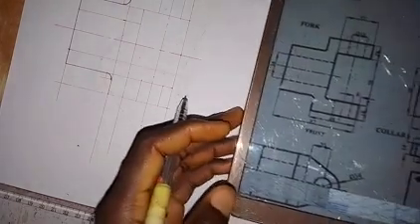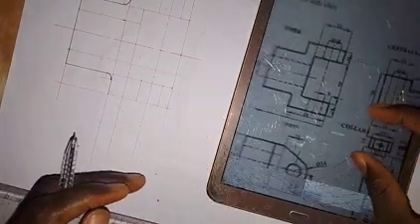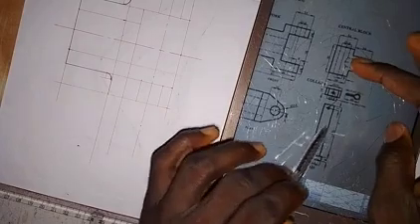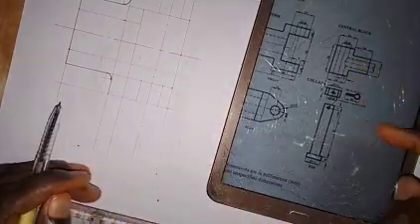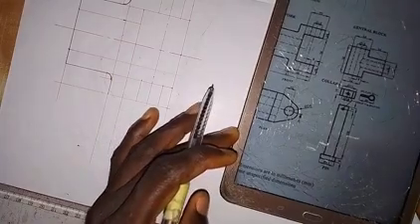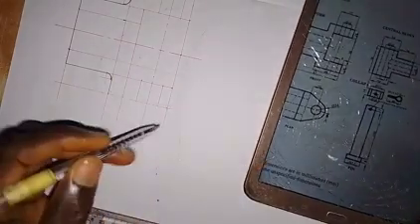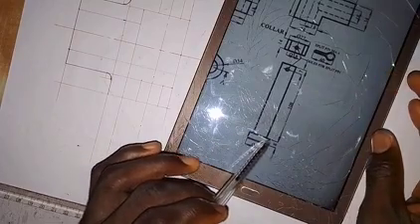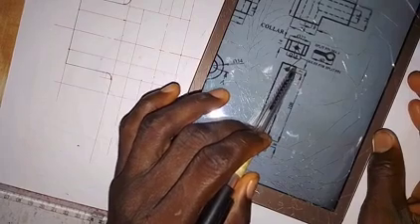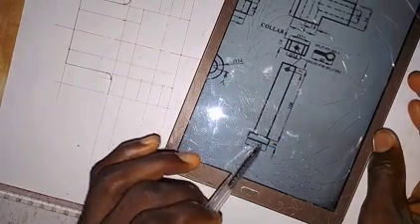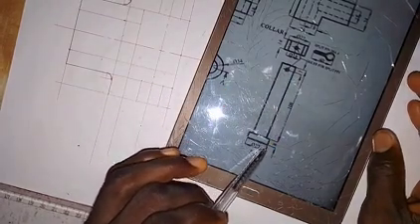Alright, we need to go on and insert the pin, and also we put the collar. So the pin and the collar as we have here, we have to put them there. With the split pin that we have here, so let's do that. For this pin, the distance from this end to this end here is 108, and the distance from here to here is 8.